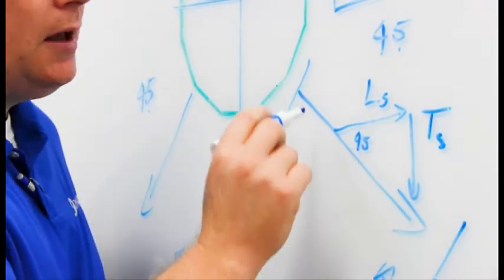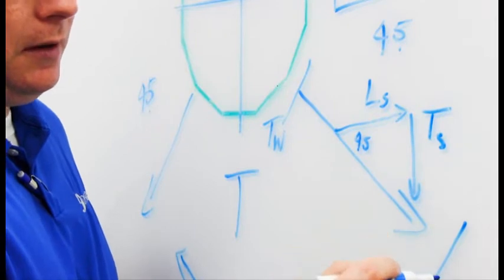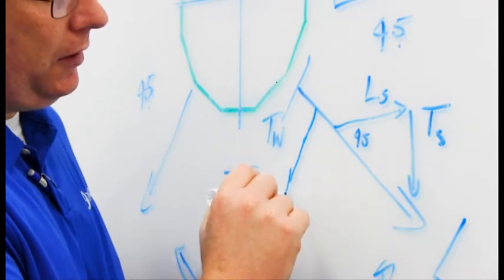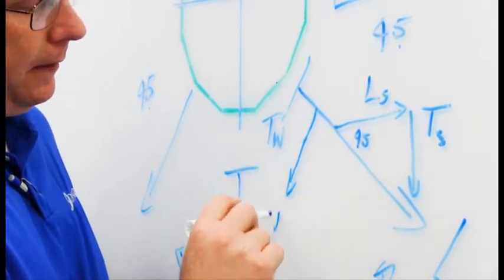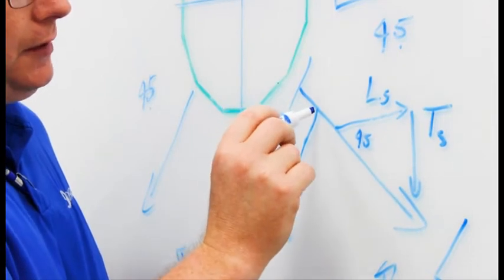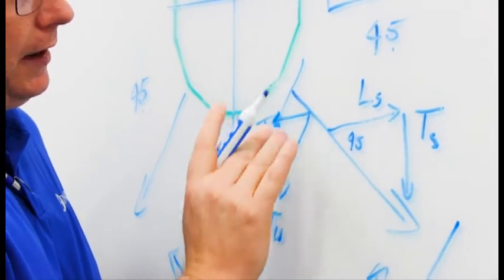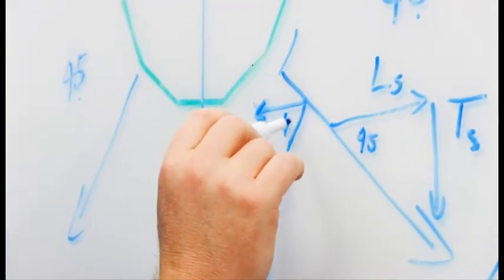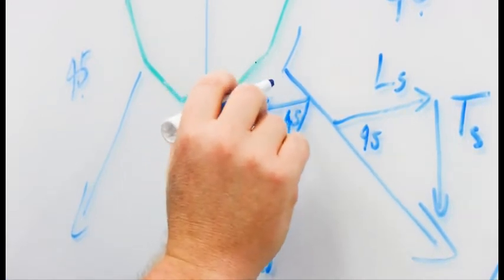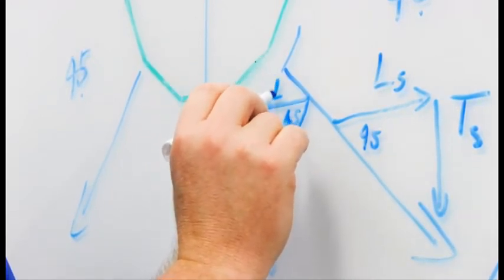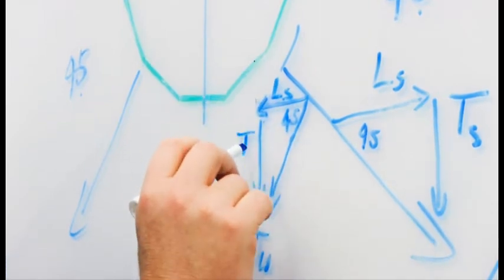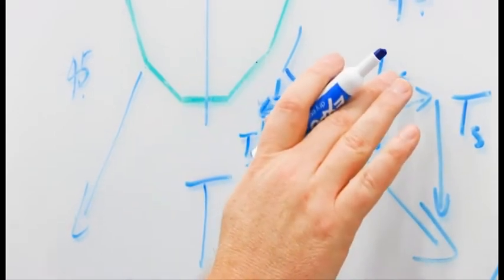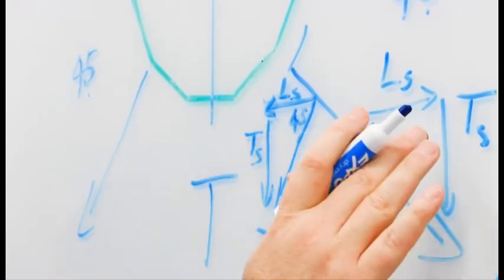And you don't want to forget, if they give us a longitudinal component for the wire, they'll give us a transverse component for the wire. And we also need to break that up by putting our vectors in there. This will also be 45 in this case. And then this will be another longitudinal component for the structure, and then another transverse component for the structure. So you can see the longitudinal components actually subtract from each other. The transverse components add together.